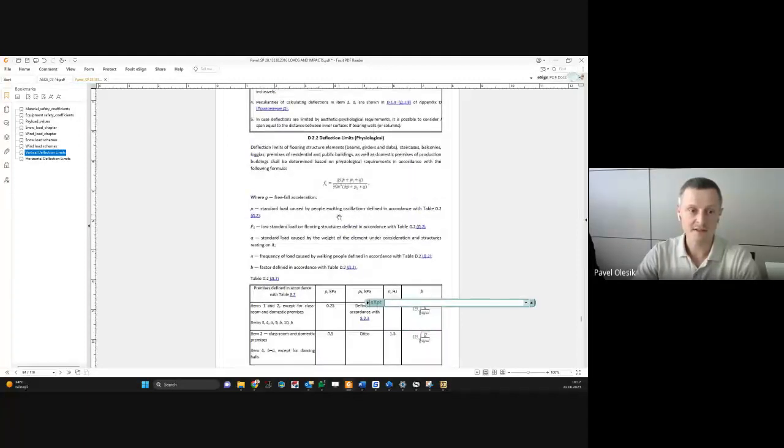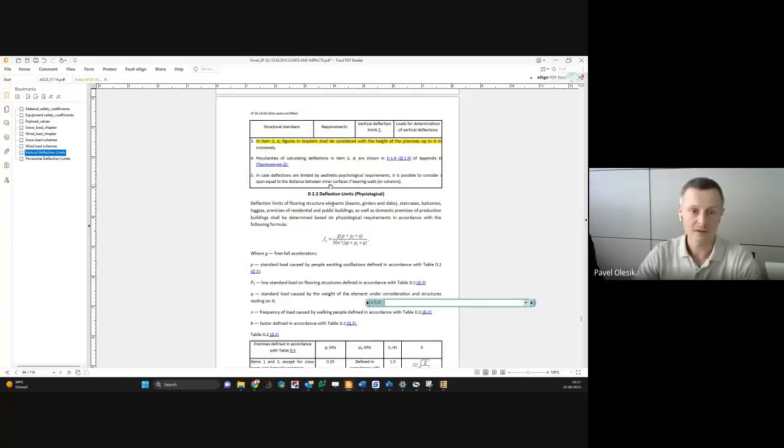In some cases it gives us a good benefit with some structures. If our element is governed by the SLS limit ratio, we can decrease snow load and get more economical solutions for our calculation.